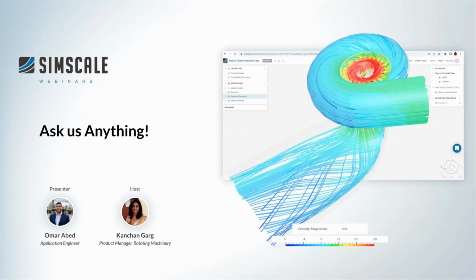I'll just start with turbulence models. The implemented model is K epsilon with specific coefficients and wall functions tailored for turbomachinery analysis. Within our subsonic solver, we do not have any other turbulence models available. This is also because this is an industry validated tool which has been around for about 10-15 years. This is an integration that we do with a development partner, and it does really well already for flow control and turbomachinery aspects. In future, there might be an avenue to add more turbulence models, but that is not something we are focusing on in the short term. And in terms of the convergence method, it is a SIMPLE based algorithm, a pressure velocity scheme.